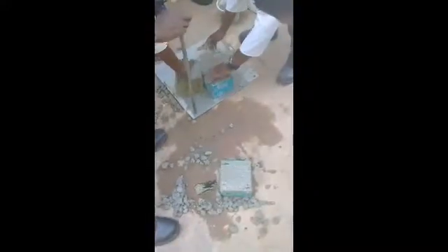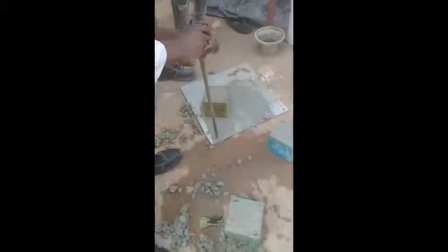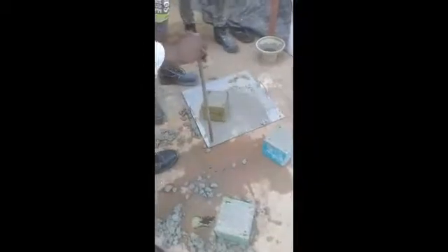After the non-stick substance was applied to the cube molds, concrete was then compacted into the cubes. The compaction of concrete into the cubes was done by the method of tamping. Three layers were tamped into the cubes, with each layer being tamped 25 times to ensure an even distribution of concrete inside the cube.